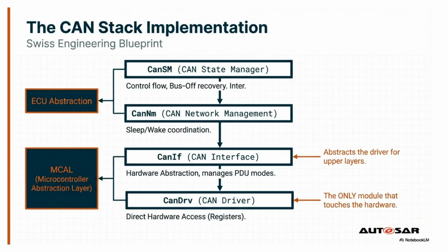Focusing on the CAN stack implementation, we see how specialized management modules coordinate to handle the most common automotive bus. The CAN State Manager, CAN-SM, implements the control flow for the bus, managing procedures like startup, shutdown, and the recovery from critical errors such as bus-off conditions.